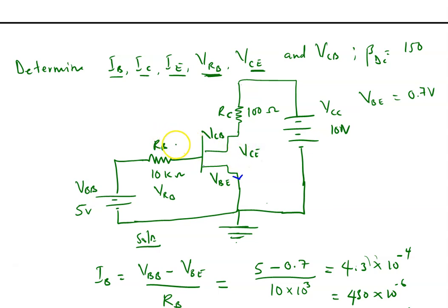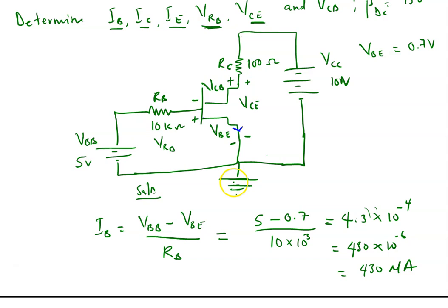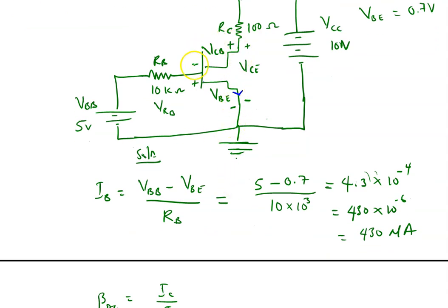And we know that this is plus minus, plus minus. But if you are focusing on the KVL on this loop, then traveling from this side, I will consider negative first. So I can say that minus VCE plus VCB, then minus VBE is equal to 0. Yes, that is KVL on the loop here.